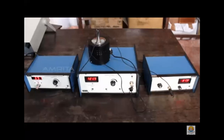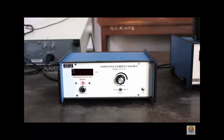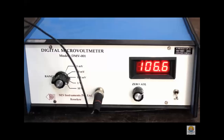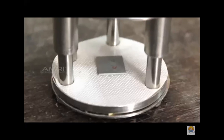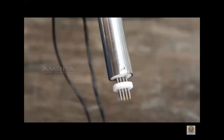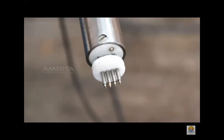Apparatus. The experimental setup consists of a probe arrangement, sample, oven measuring 0 to 200 degrees Celsius, constant current generator, oven power supply, and digital panel meter measuring voltage and current. This method is employed when the sample is in the form of a thin wafer, such as a thin semiconducting material deposited on a substrate, of thickness 1 millimeter.